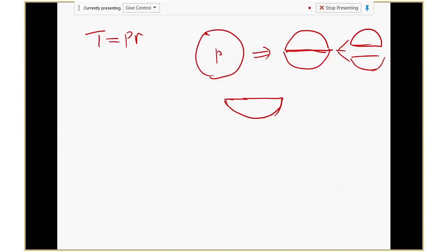Under pressure, can I find out the stress in this arc part? I can do it by making a cut, right? So I can cut here, cut here. So I end up with one at the top, a plate, and at the bottom this half circle. It's under pressure P, right? So pressure P is still here. Now, what's the tension here?